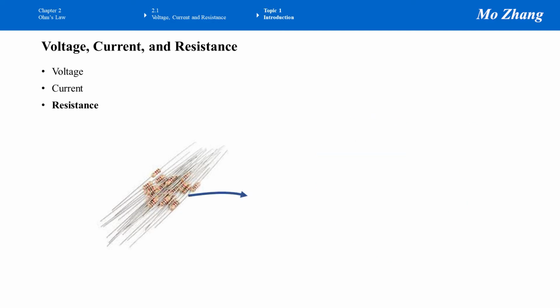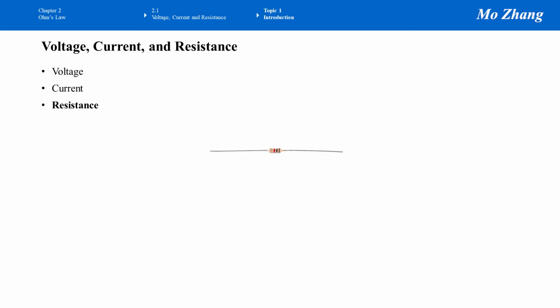Pick one resistor and then put it in the center. Rotate it and then let's zoom in. As you can see, this resistor has 4 color bands. If you read from left towards right, the first color band is gold. If this is the case, the resistor is in the wrong direction, which means we need to flip this resistor. The last color band, the color band all the way to the right, should be either gold or silver.